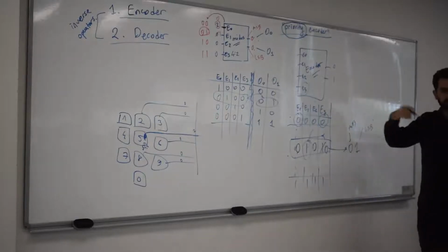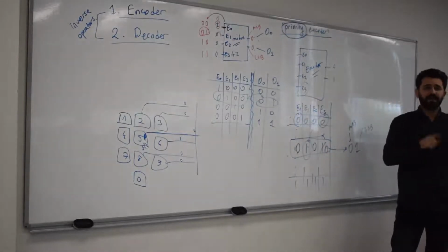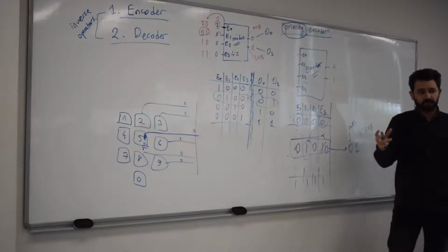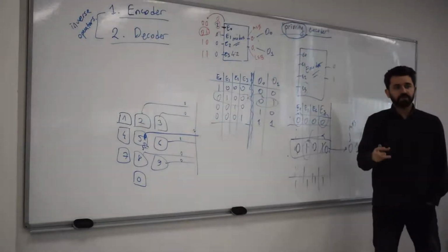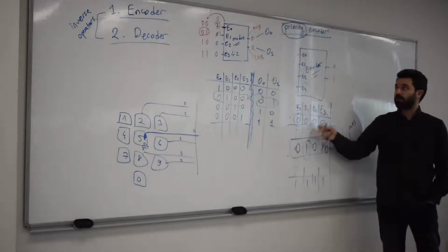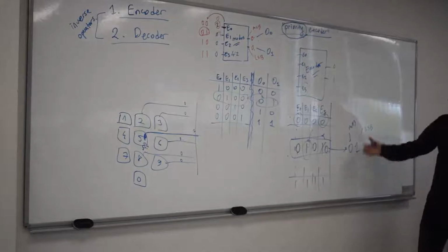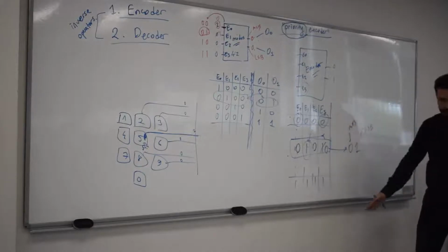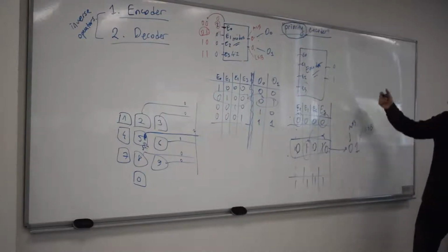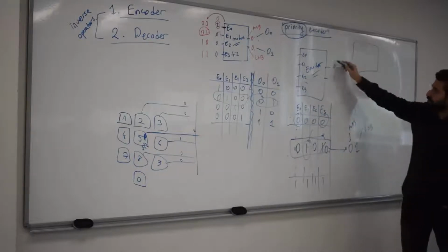And we actually did this, so I'm not going to go into the details. But in our last online meeting, we talked about this, and I came up with some Boolean expressions, if you remember. Those Boolean expressions belong to the analysis of the truth table of this priority encoder. So if you do all these mappings, you can draw the Karnaugh maps for each one of these outputs.